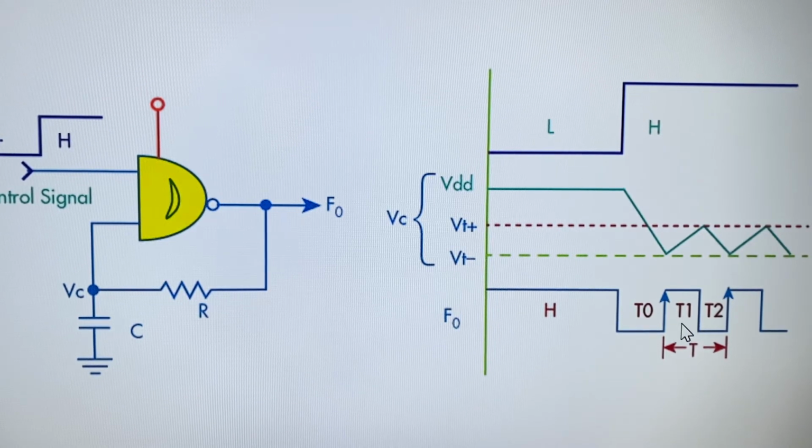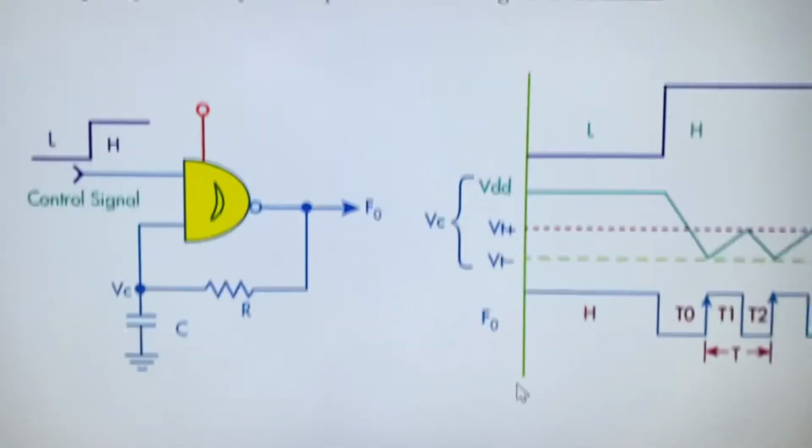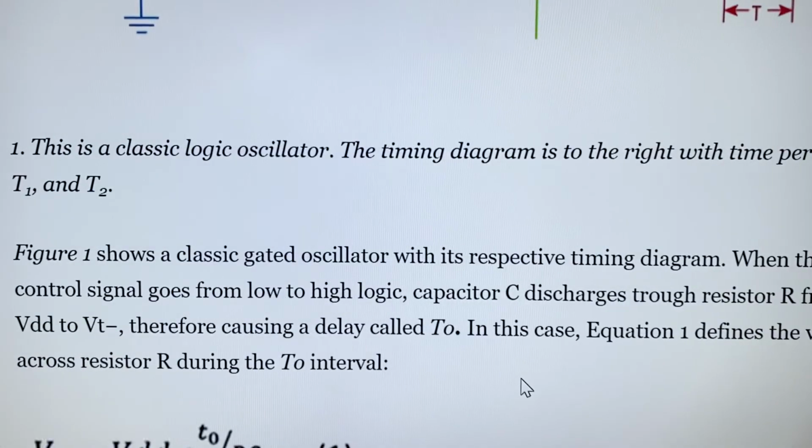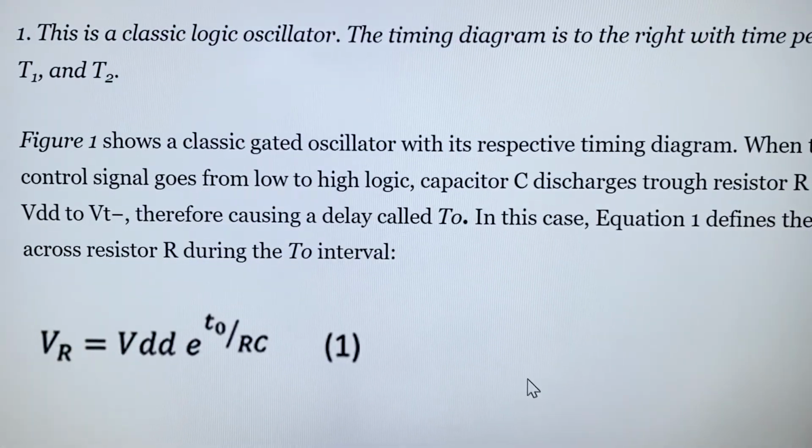But the problem with this oscillator is T0, because it took this time to start charging. This presents a problem when you are using these oscillators in instrumentation applications as a base frequency oscillator. It will always affect your readings. Of course, you can adjust it with other techniques, but they will not be accurate. Now, to solve this classical problem, I have here a solution.